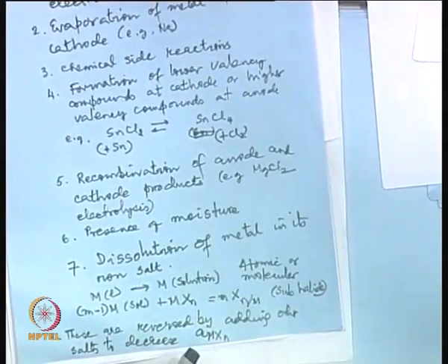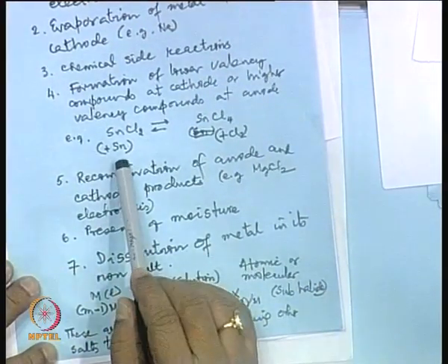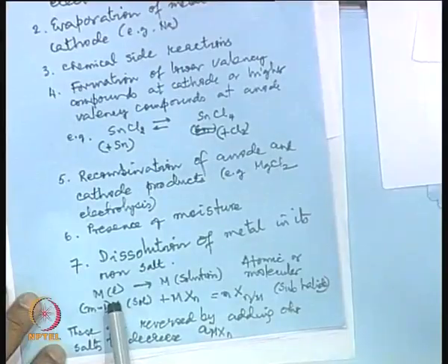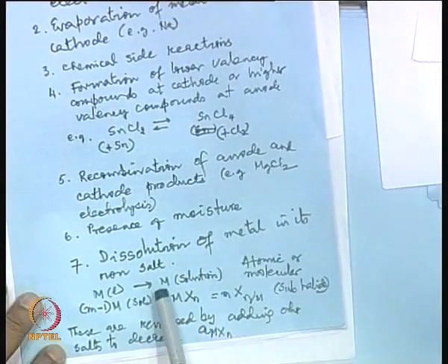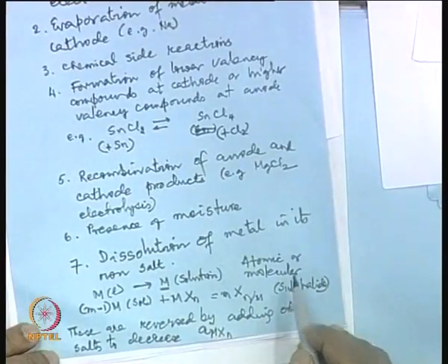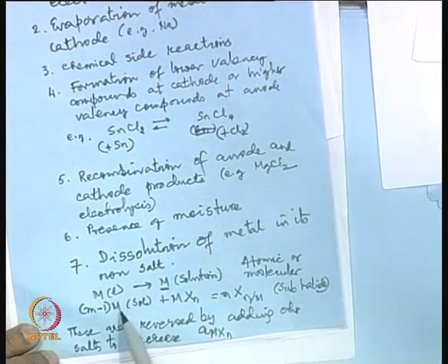This has been studied very thoroughly, and the present theory is, of course, metal can dissolve like this, that it reacts with the bath, but we are not talking about a situation where the metal is reacting with the bath. The metal, say it is a liquid metal that has been produced, can actually dissolve atomically, means can go into the atomic spaces in the supporting bath. It could be atomic or it could be molecular. Then from that state of solution, it reacts with the salt that we are trying to decompose to produce a subhalide.